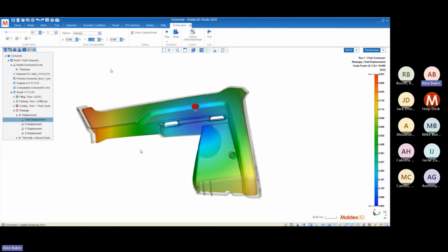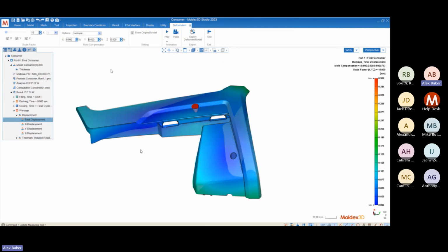5,000ths of an inch per inch shrinkage, or 0.5%. All right, so I'm going to input 0.5 because we're using isotropic compensation. All three directions are going to have the 0.5 compensation applied. If you want to apply different compensation values, you can use anisotropic.